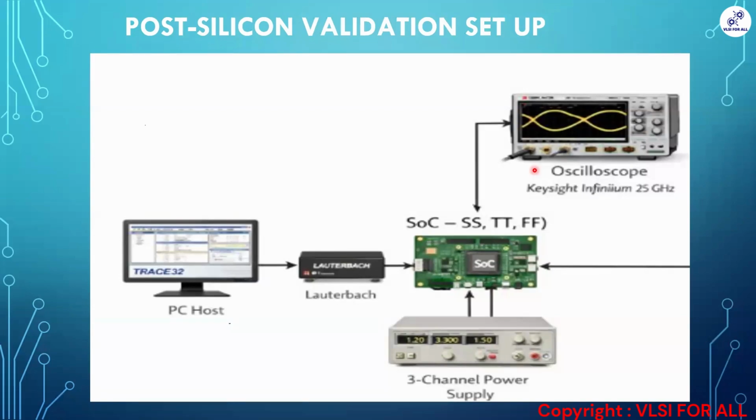There will be multiple hardware instruments. From a basic point of view, you should know how to use the power supply, the DMM, the signal generator, the source measure unit SMU, and the oscilloscope. Thermostream and other things are industry standard, but basically you have to know how to use the basic hardware equipment. And second, you should know how to read the schematic of any board or any IP.